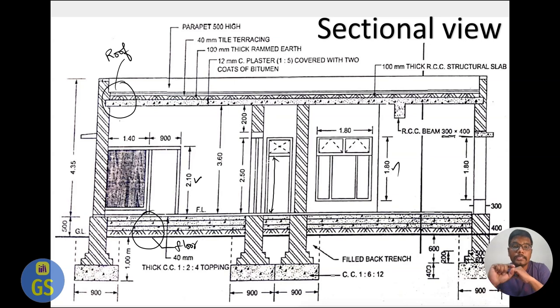So those details, what is the thickness of the tiles or thickness of marble which you are going to lay in your house. Those thicknesses and the layers, how many layers, like fillings, sand filling or compaction. So these are the things which will be shown in the sectional view. This is the main reason why we are preparing a sectional view as part of the diagram.